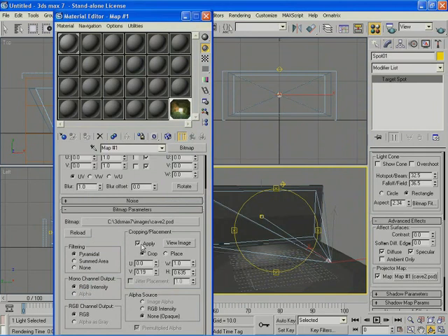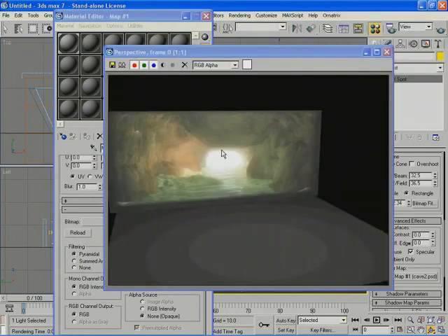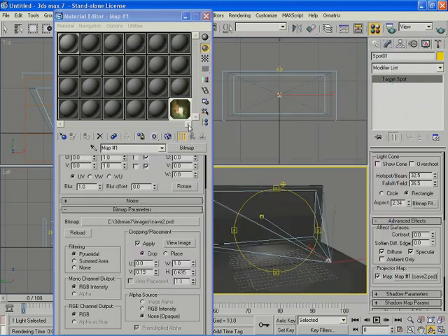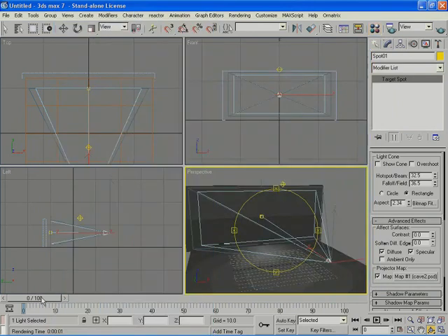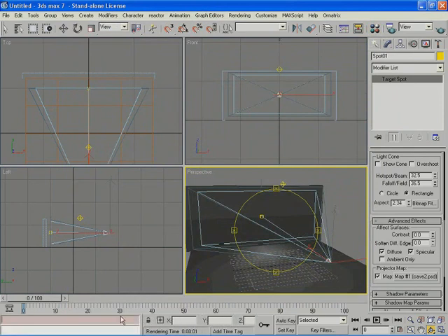So in case your footage did not have the proper ratio of the projected surface, which is in this case around 2 point something, 2.3, you would take that image into the material editor, drag it, go to view image, and make that image have the same proportion as the other one. Now, how can I know the proportion? Here I have the width set to 1 and the height set to point this value. So I'm going to go here to my max script listener and choose 1 divided by that value and press enter, and this is going to give me the result. So here in this case it's 1.6. So I need to make it even smaller so that I can get 2.3. That way you can get the exact same aspect ratio that you're using here. But otherwise, so far it doesn't look all that bad.